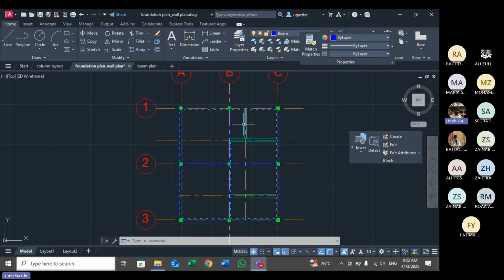But if you give a beam here, then you can see this one and this one is a very small span. So it can work without this beam as well. But this one, you can see this span is almost equally divided. If I give a beam here, both the spans are almost the same. So we can have a secondary beam over here and we can have a secondary beam over here.